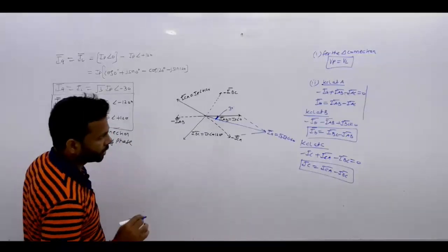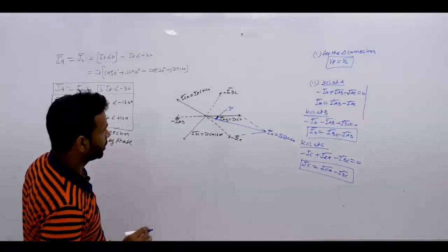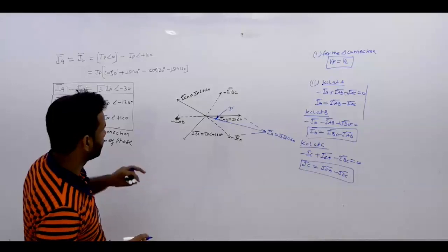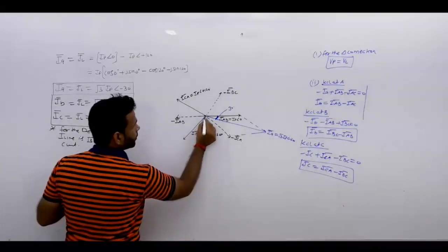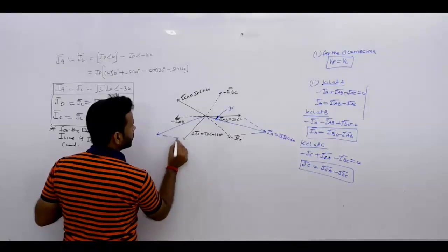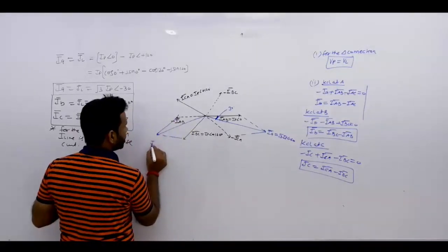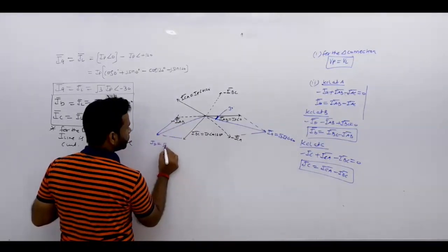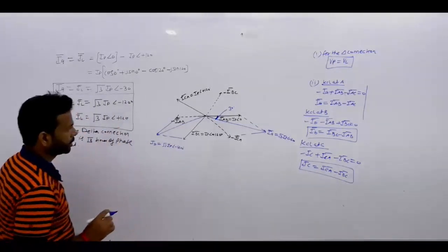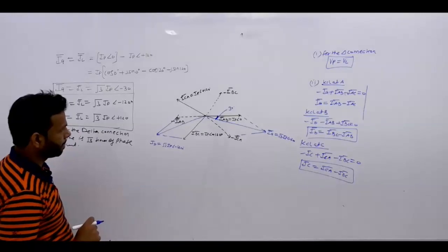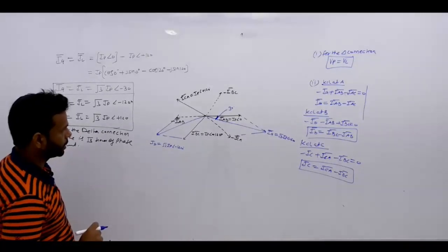Similarly अगर हम second current की बात करें तो IB is what? IBC positive minus IAB. This is your second line current. IB is equals to √3 IP angle minus 120 degree. Okay. ठीक है यहाँ तक ना. Next अगर हम देखें minus 120.